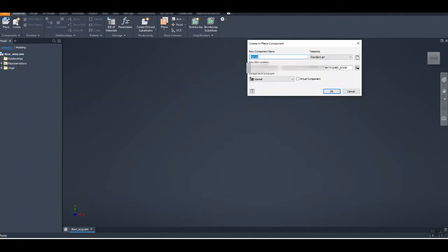Create the first part, and the first part is going to be called the frame layout. And then project shed door, just a regular shed. Gotta delete that out. Okay. Make it a reference, default BOM reference. Why you pick reference is so the frame layout doesn't show up on the parts list. You just want it to be a reference. If you make it part normal, then it becomes part of the bill of materials.